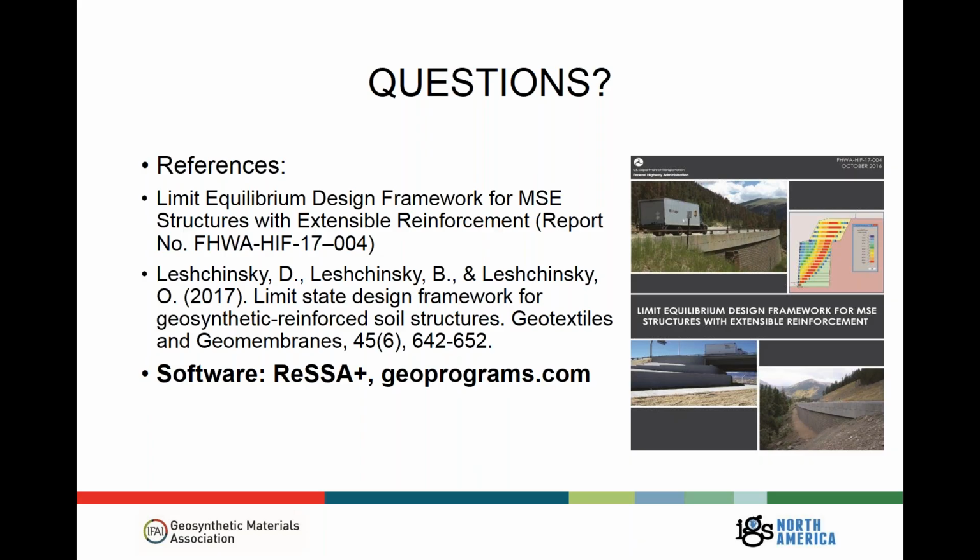And John, to your question about the phreatic surface, in all these simple examples I showed, we actually didn't account for water. But you could directly account for water, and since we're doing a slope stability analysis, that would be accounted for as a pore pressure affecting the effective stress or effective strength of each surface analyzed at the intersection beneath the phreatic surface. So you can account for water in the reinforced soil or even ponding water outside of it. But in these simple examples, I ignored water, which is a big thing to ignore for sure.